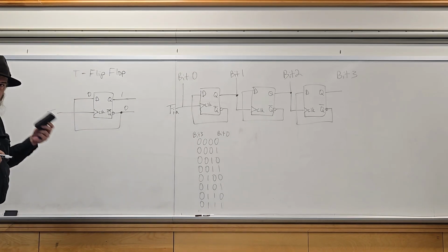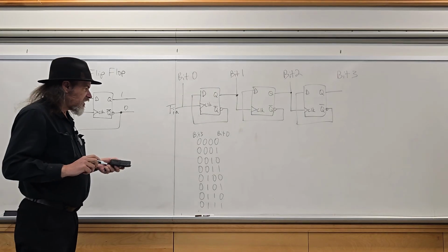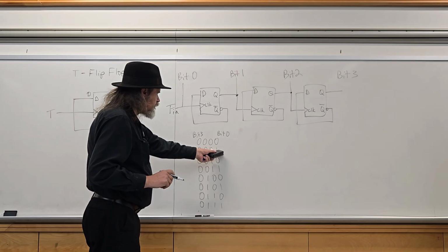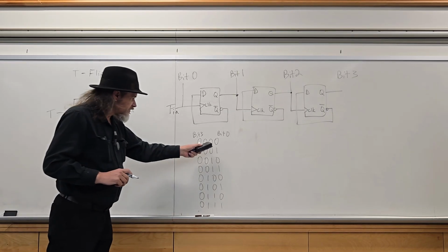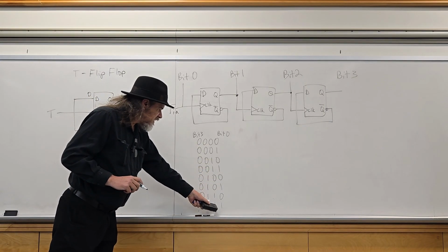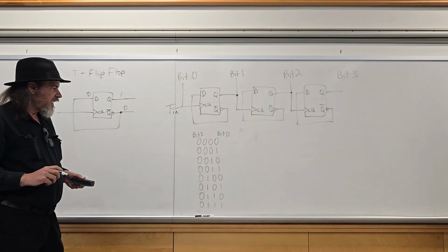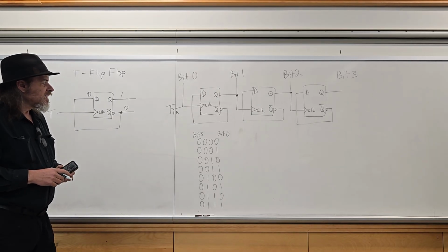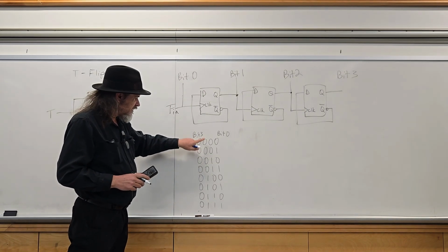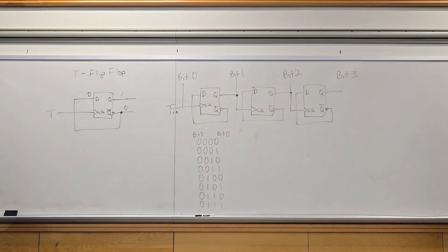Each clock cycle, it toggles between 0 and 1. At half that frequency, every 2 cycles, bit 1 will toggle and then hold that for 2 cycles and then go back to 0. Bit 2 is every 4 clock cycles. So your counter is similar to a frequency divider.